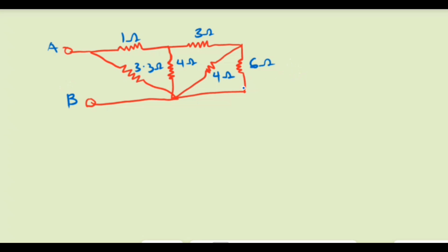Then number two, we take two resistors at a time whenever you are considering the simplification process. So if I want to start from here, I'll take this and this, but I don't take three. So let's start from the farthest end, which is 6 and 4.